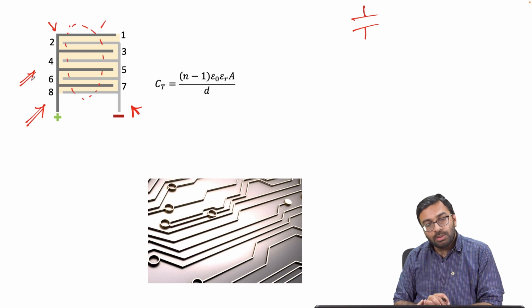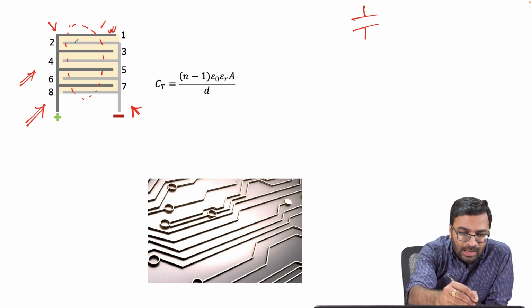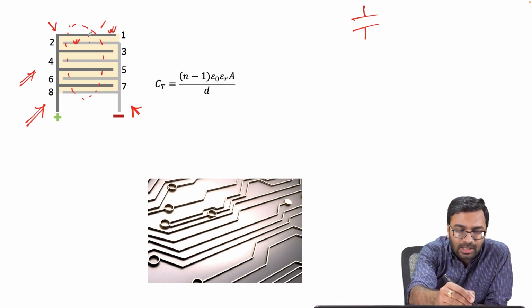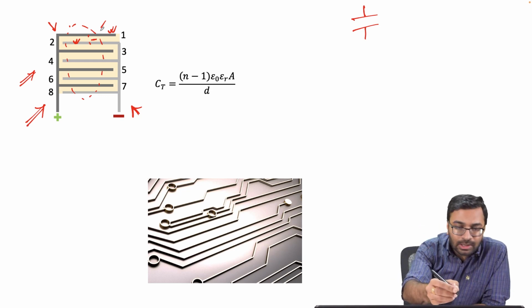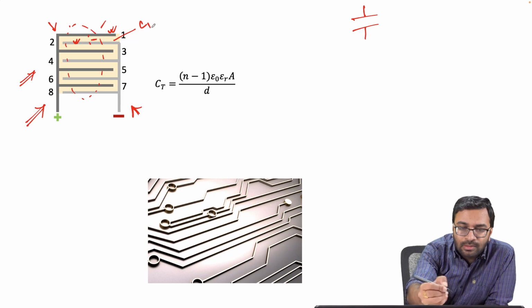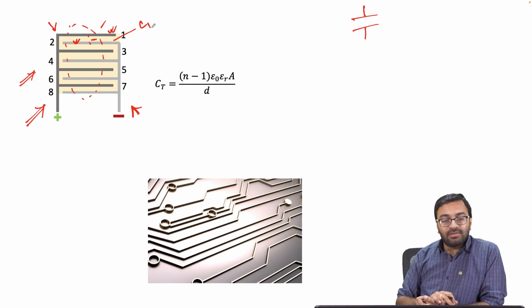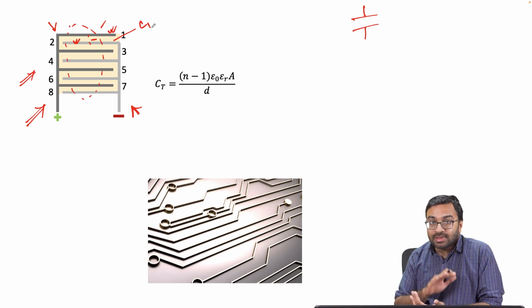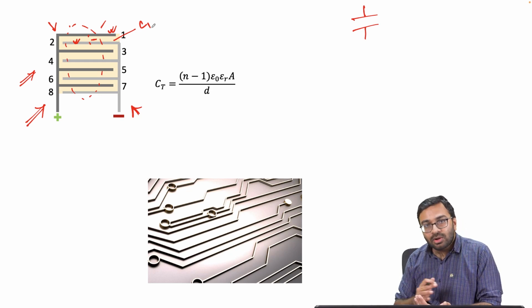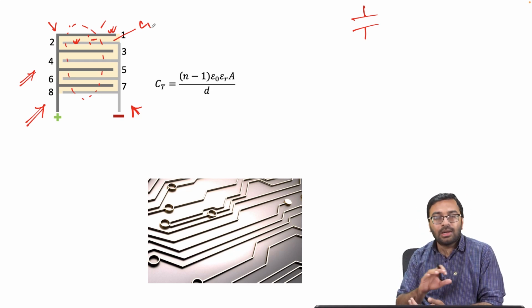Okay, but one of the problems with this type of interdigitated electrode is, this electrode and this electrode both act as a parallel plate capacitor, because both are conductors, and then you have a dielectric material, say the substrate or the air in between, acting as the dielectric. So you will get a capacitor C1 in this case. There will be a capacitive effect, and this capacitive effect may hamper the sensor performance. So it's not only the capacitive sensors. Sometimes you may get a certain sort of capacitive effect in your circuits and some other sensor, which you need to consider when you are developing the system.